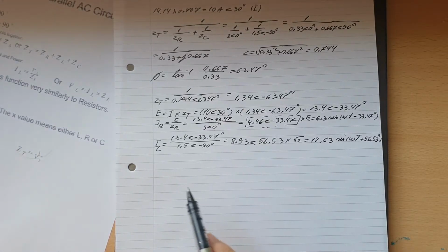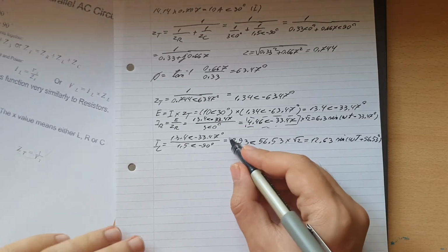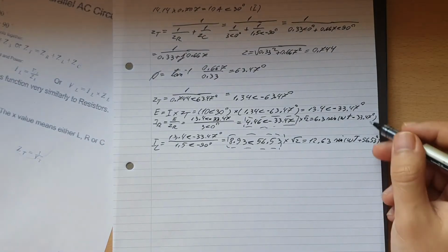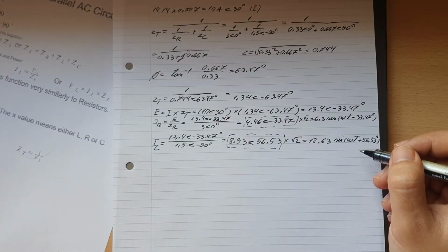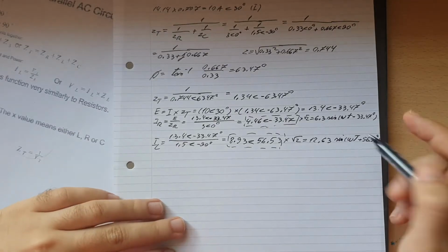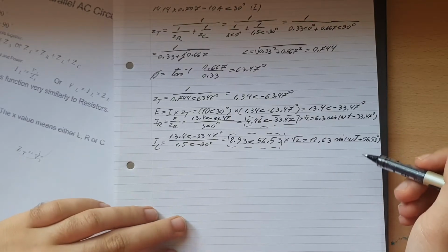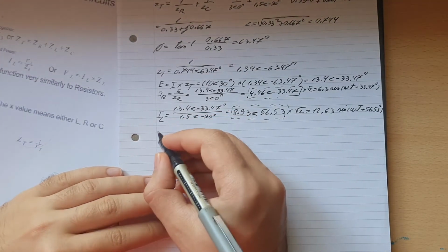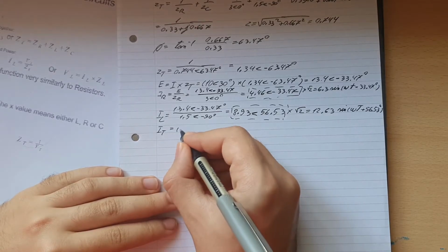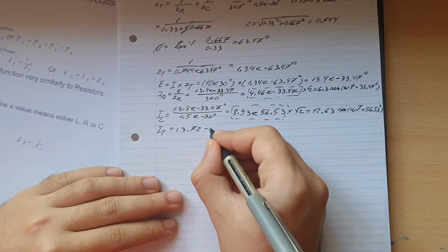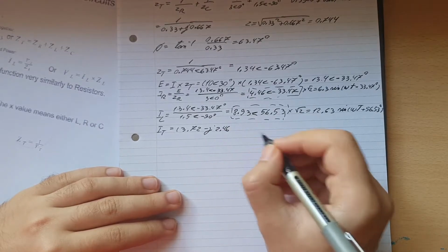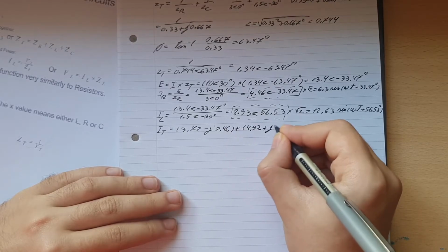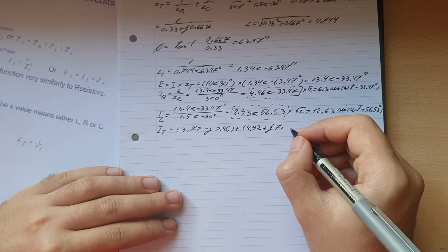So now we found out the capital value, like the RMS value, which is this one here that we boxed right now. And these two are the normal values that are used every time. Those are the peak values, you can't really call a value normal, these are the peak values. Now let's keep going then. So then IT is equal with 3.72 minus j 2.46 plus 4.92 plus j 7.8.